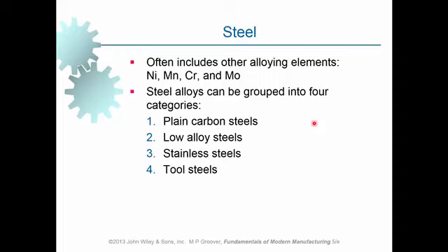We've got low alloy steels when the magnitude of the alloy elements cannot be ignored. However, it's not much. Of course, we have got some high alloy elements which are not listed here. These are the ones that are of common use. Low alloy steels are used to enhance certain properties of the steels, for example, strength, resistance to wear, and resistance to corrosion.